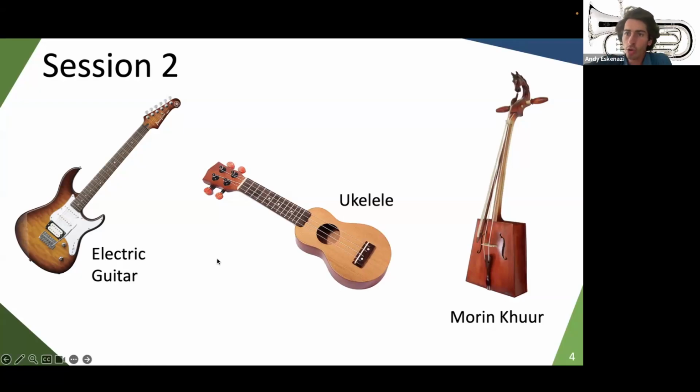And then in all subsequent sketches, we're always going to use the command that we learned last time, which is the project command, and reference our subsequent sketches based on the primary one. The primary one is also known as the master sketch. So you just reference that, and add a layer, a layer, a layer on top of each other. You'll see that that will be sufficient for us to CAD these three objects. So let's go ahead and get started on Creo.